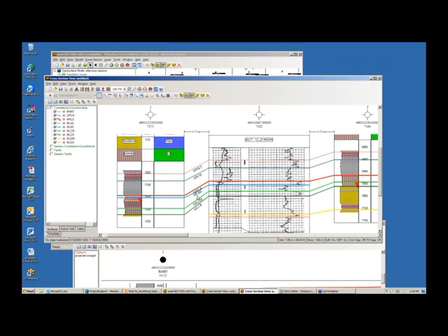You just need to know how to get started to set up that performance, those 6 items where you're making sure that your surfaces are in their correct position, that you've got your sources picked, and that you're modeling the picks that you've always had. So at this point in time, any of you could pop into your projects and go ahead and open up a new interpretation and go to GeoSurfaceModel Properties, select the formations that you wish to use if you know what your source is and if they're in correct chronostratigraphic order. So that's basically all I was going to discuss right now.